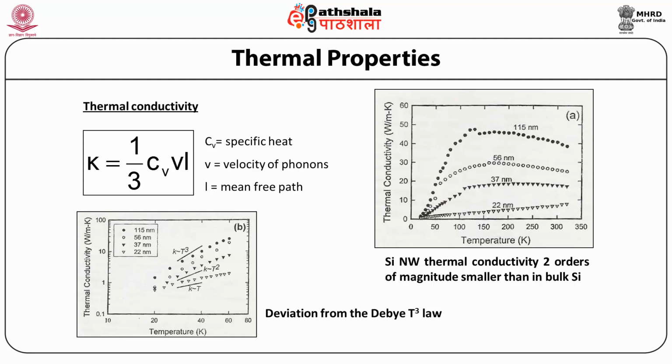Measurements on mats of nanowire do not generally give reliable results because the contact thermal resistance between the adjacent nanowire tends to be high, which is in part due to the thin surface oxide coating that most nanowire have.